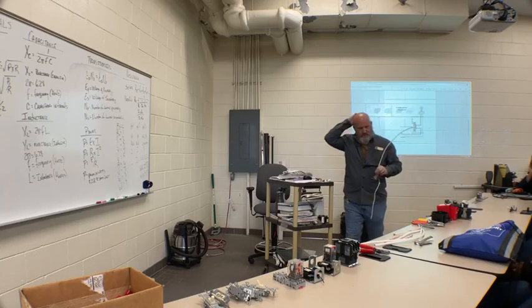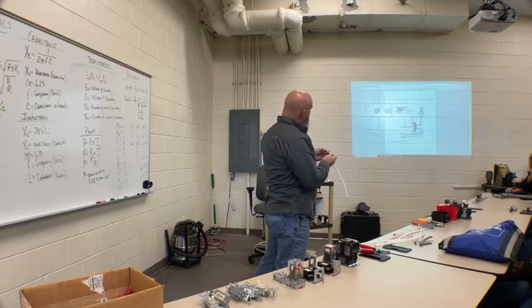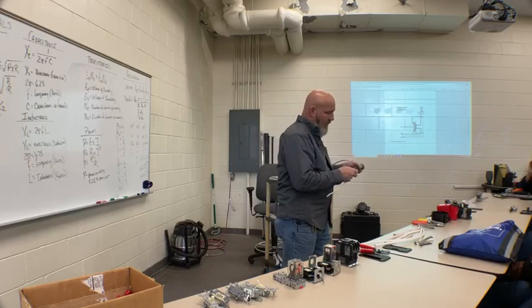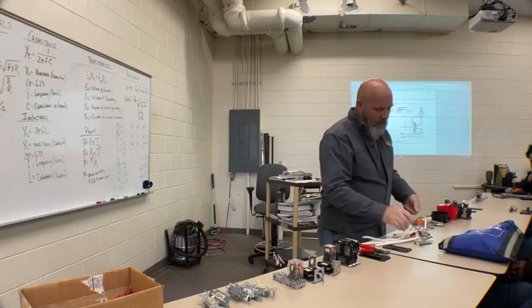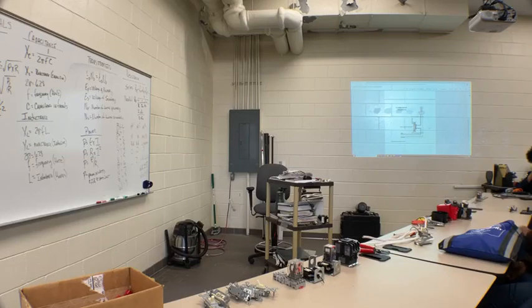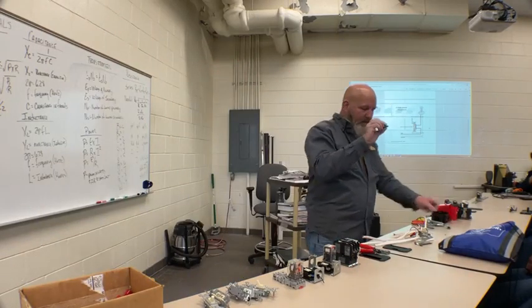That's what that is. What's the copper wire? Yeah, the copper wire is for the ground. Oh, okay. That's not shown on there, but you would actually twist them together and hook them to the ground wire. And for grounds we have a special wire nut, which I'm glad they invented because back in the day they had to twist everything together. The only time you can use this is on the ground, is a green wire nut. It has a hole in the end of it.